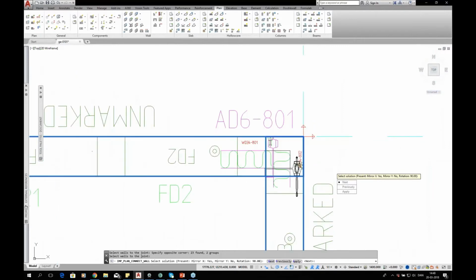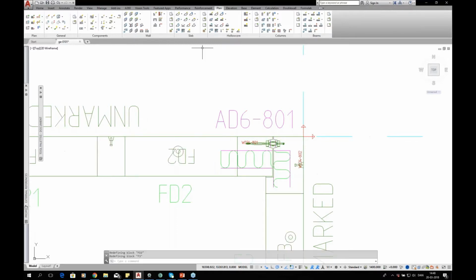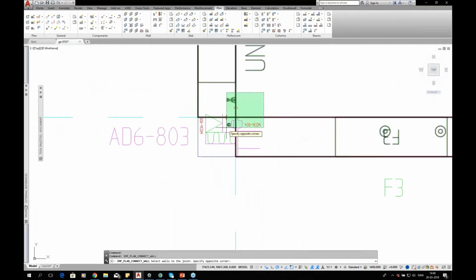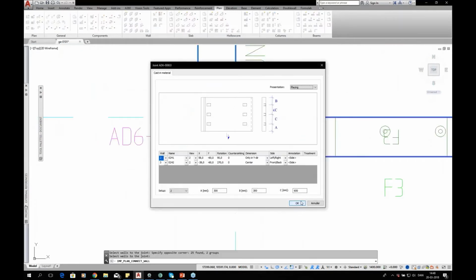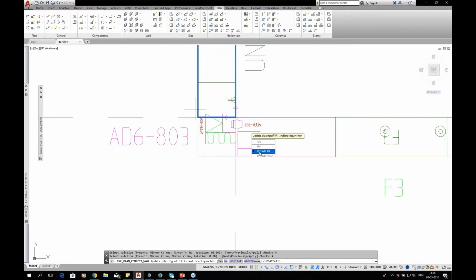And as some of you may have noticed, when I mark the elements, sometimes I mark the underlying drawing as well. This doesn't really matter. I just mark it as quickly as I can because IMPACT can tell which is an IMPACT element, which is just a regular AutoCAD polyline or AutoCAD drawing or whatever it might be. So the system quickly recognizes everything it needs to.